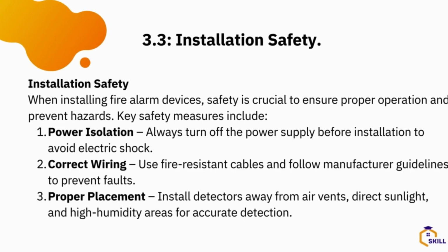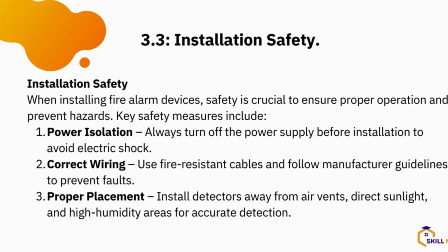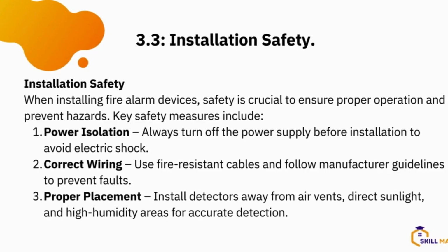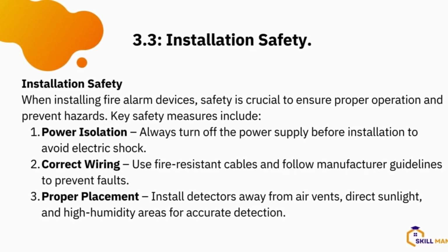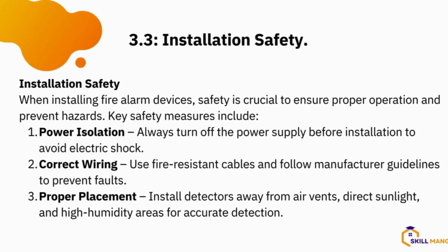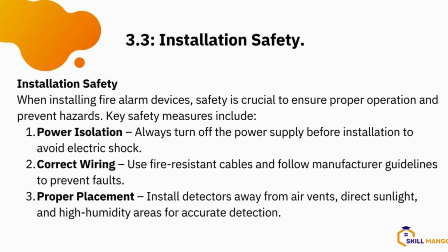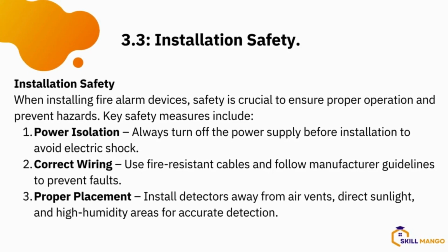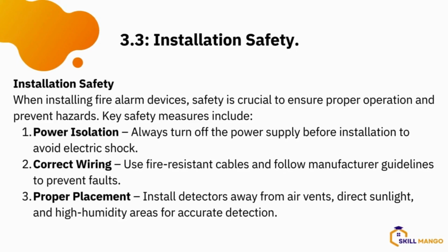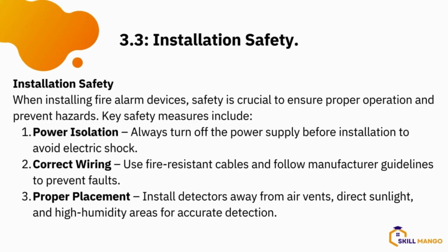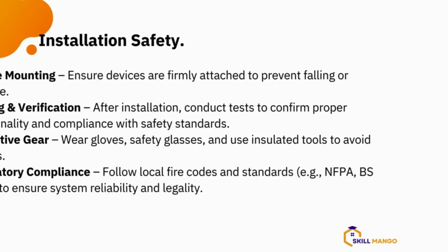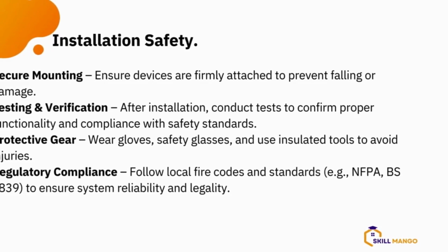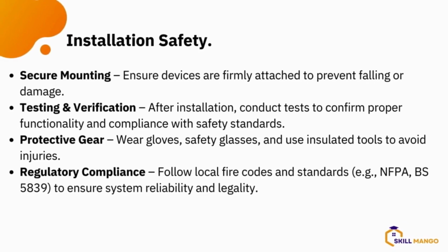Then use the correct wiring. Make sure you use fire resistant cable. Then you follow the guidelines of the manufacturers when you are deploying. Then proper placement: install detectors away from air vents, direct sunlight and high humidity. These are the measures we have to take. There are a lot of them. You can also look at secure mounting, testing and verification, protective gear, and regulatory compliance. These are very important when you are installing.